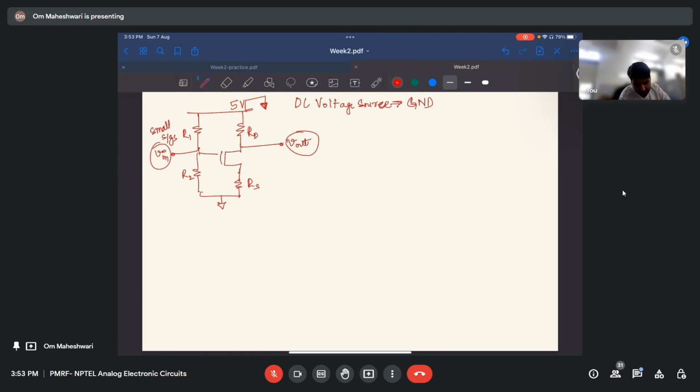So why is this happening? What is a small signal actually? Let's say this is a DC voltage, let's say VD, flowing through some wire. What is a small signal? We apply a very small time varying signal over it. That is small vd. It's a small signal applied to the existing DC signal.